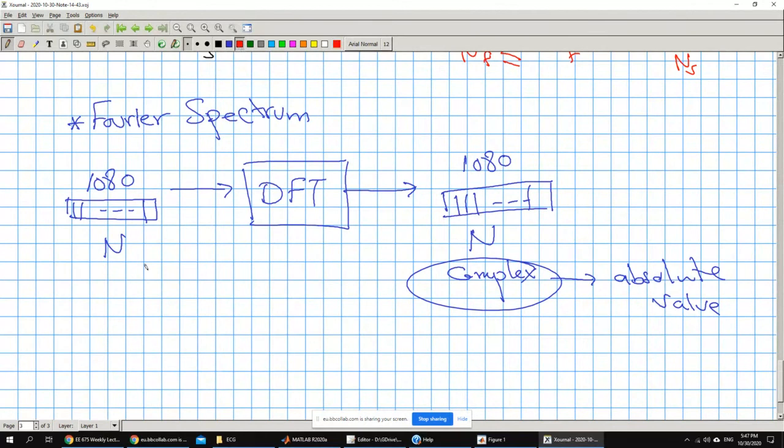But we have to notice a few very important things. Because we have real values here, we will have a symmetric spectrum. As we saw before, if we have something that looks like this here, it is equal to exactly like this. So if we take the whole thing, each one of these values will be doubled. The value here will be exactly the same as here, and here the same as here. So what I should do is just take half the data.